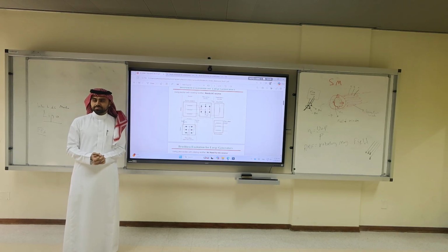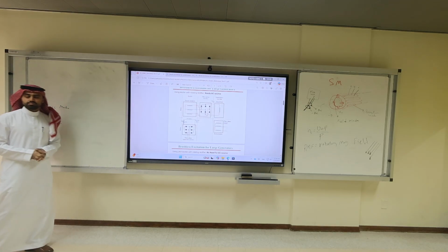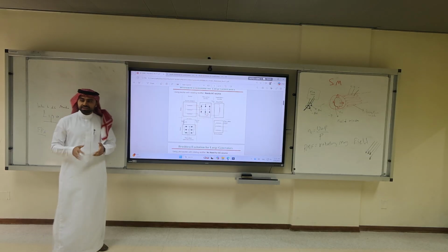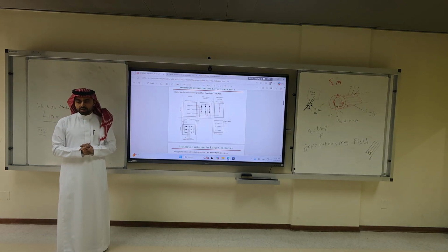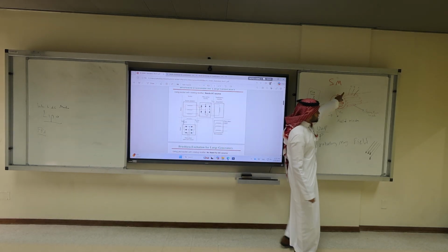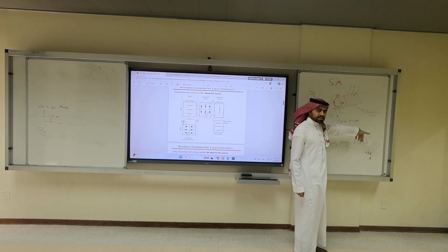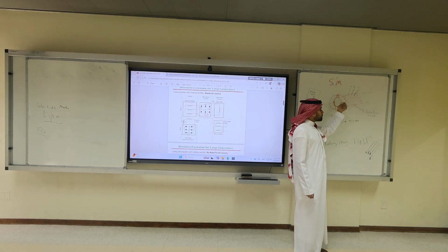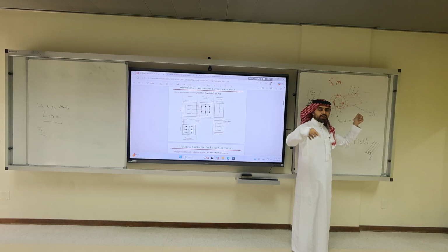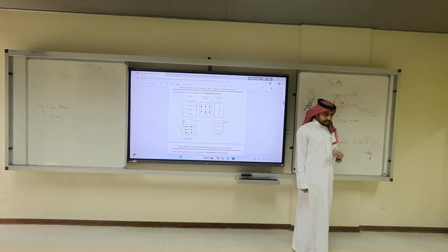Yes, what's the question? Now, the current you apply, the final output is on the rotor itself, right? No, your final output, let's say for a generator. For a generator, you get small AC, you rectify it. Okay. You apply it at the stator. You have constant magnetic flux. This constant magnetic flux induces nothing on the rotor. Start spinning the rotor. The rotor is connected to nothing currently. We are a generator, so we need the prime mover. A diesel engine moves the rotor. The rotor would cut the flux lines, right?